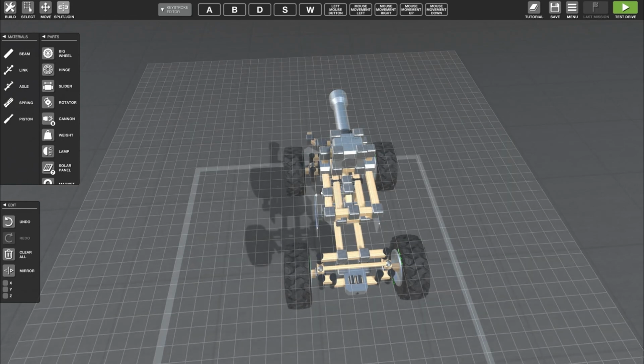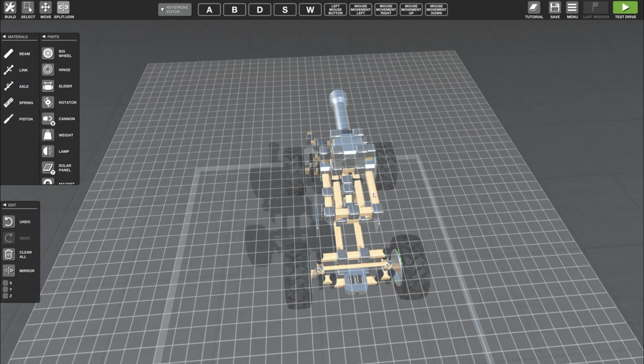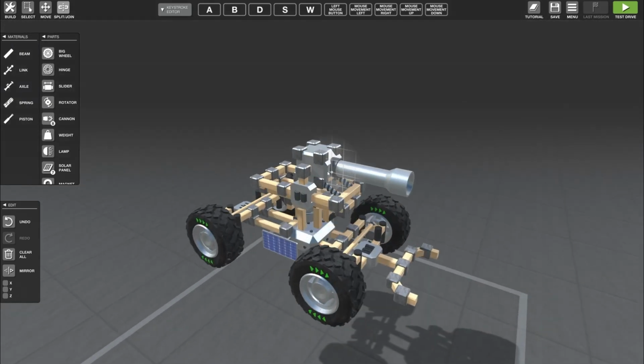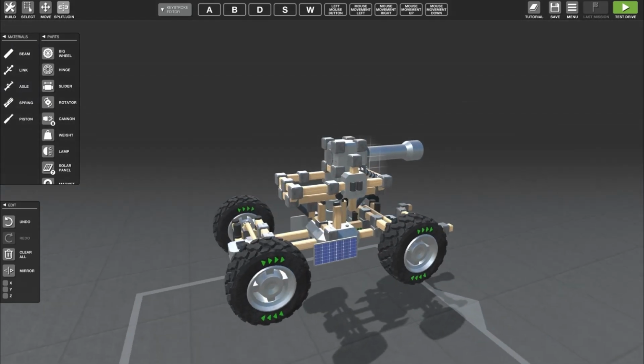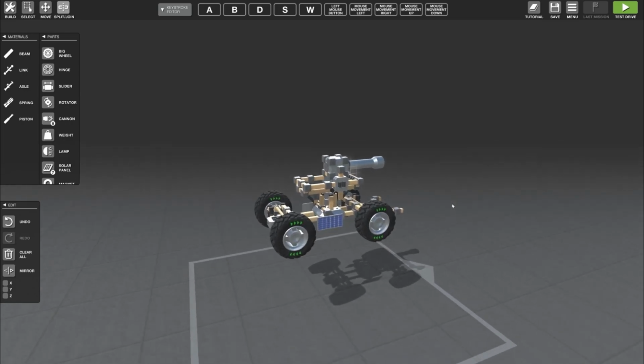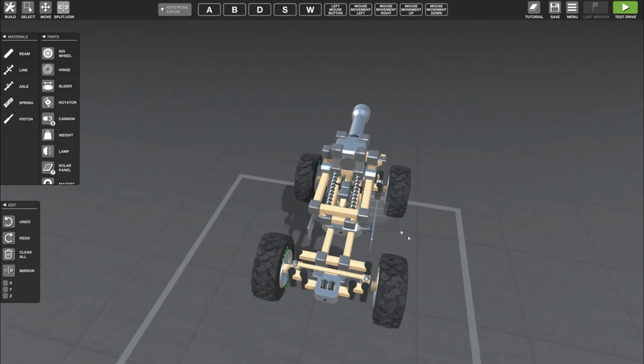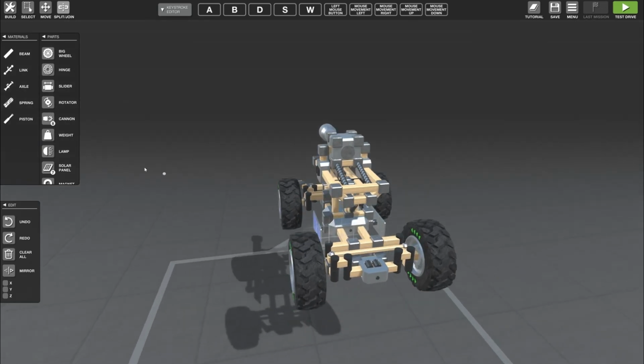Simply select the tool and draw a line across the material you need to split. The join function can be used for instances when you have a beam in multiple pieces, separated by these joint nodes, and need it to become one continuous piece. In order to do so, select all the beam pieces needed, click on the split join button, and this will convert them into one continuous beam.